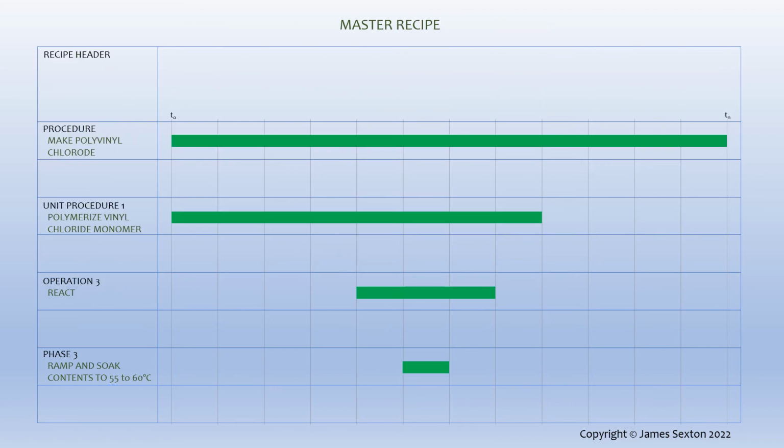Recipes are the complete instructions to make a product. Once a procedure has been defined, it will form the sequential part of a recipe. For the explanation that follows, we will show just one element for each of the procedural control levels. The template for a specific product on a specific site is called a master recipe. It will consist of a header with placeholders for parameters and any unique identifiers, plus a reference to the procedure to be followed. Normally, each procedural element will be adaptable, with some input process parameters that allow different grades and quantities to be made. For example, temperature set points.